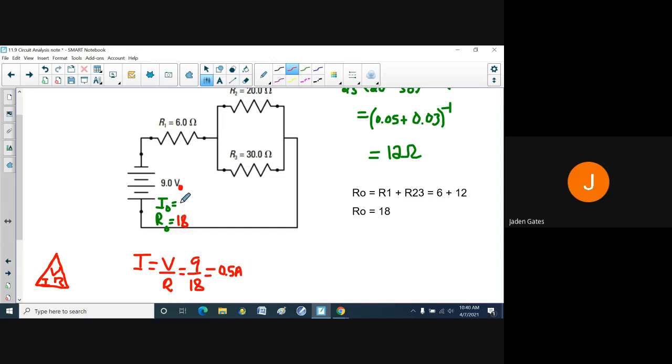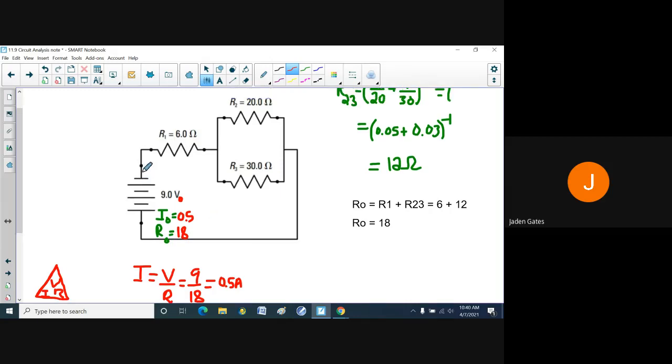All right. So there we go. I got that piece, 0.5 amps. Now, that means 0.5 amps leave this circuit here, and that means they have to go through the first load. All of them do. 0.5 amps. Now, that means actually I can find the voltage, because again, I have my V equals IR formula, or my Ohm's law triangle here.